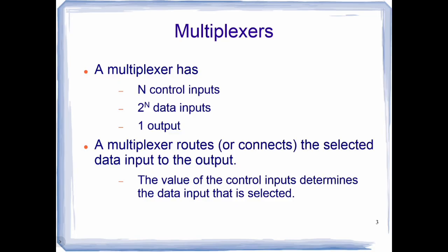Since a multiplexer selects one of the inputs and routes it to the output, it is known as a data selector. Normally, there are 2^n input lines and n selection lines whose bit combinations determine which input is selected. Therefore, a multiplexer is many into one, and it provides the digital equivalent of the analog selector switch.